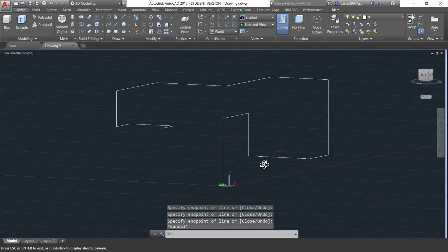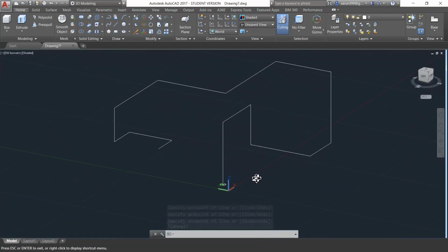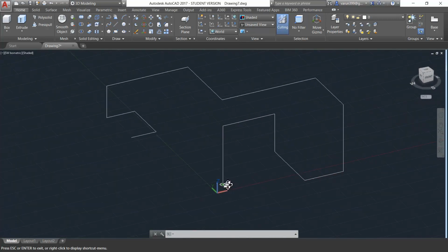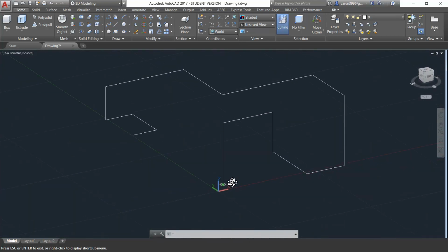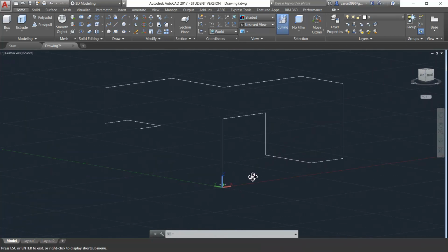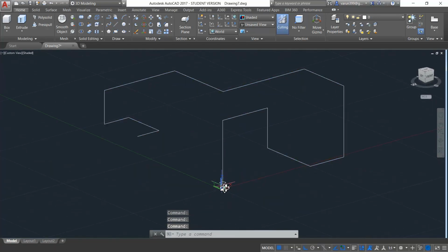So when you revolve it, you can see it is showing as a path. It is always better to check by revolving your drawing whether the object you have drawn is now in the z-axis. Sometimes what happens is that you may be thinking the objects are in the z-axis, but eventually the object may be drawn only in the xy plane. Now after drawing my 3D polyline, you can check the polyline is a single object. So now your path is ready, your cross section is also ready.